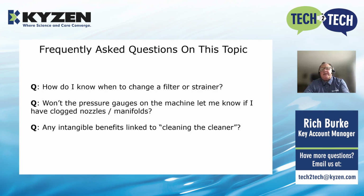So if I look at a pressure gauge when I have clogged nozzles and manifolds, I feel great, but I might not have any flow. So I'm potentially having zero cleaning or very little cleaning going on, but the pressure gauge tells me otherwise. So it can give us a false indicator. In an ideal situation, we might have a pressure gauge and a flow meter or flow sensor together that can be very helpful and very useful.